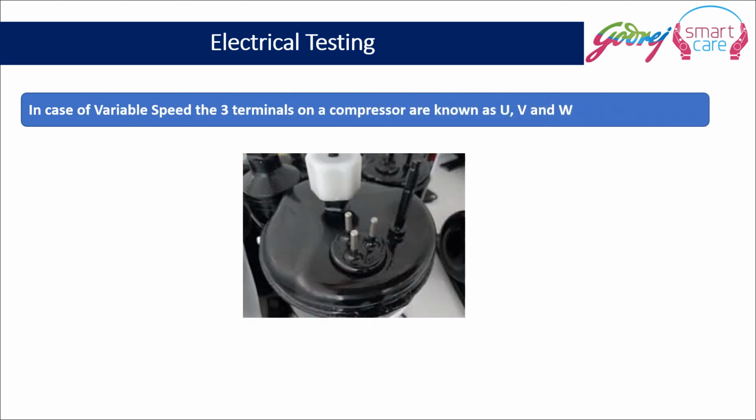In case of variable speed, the three terminals on the compressor are known as U, V and W. We will test for short winding of the compressor.